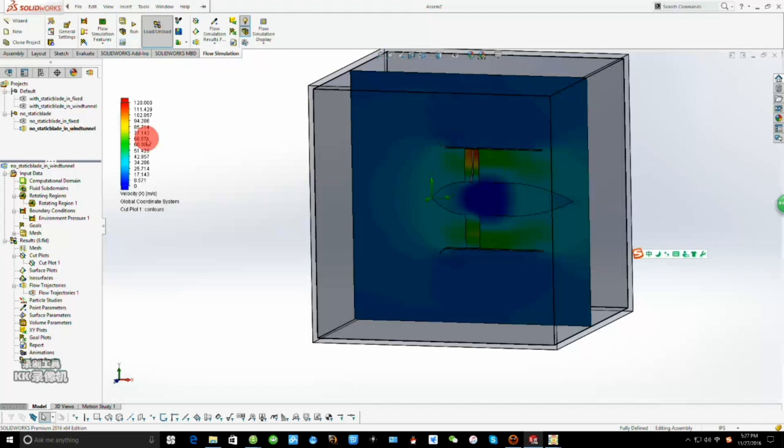We hope you enjoyed it, and as we also set the max velocity to 120 meters per second here. When we were testing this on our own, we had it at different values. About 130, 120, not really a difference, but at 150, you can't really see a huge amount. This area at the front wasn't visible. It was the same color when it came to showing us the flow trajectory and the velocity one. So that's why we ended up lowering it here.